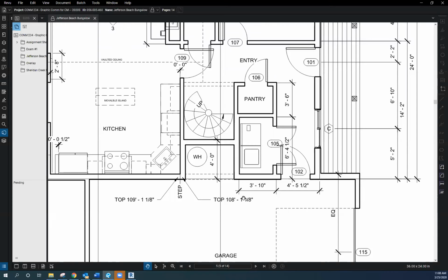The thing that's different about this wall is how the wall is constructed itself. Generally speaking, because we do have an occupancy separation, or occupancy use change, from the main part of the house to the garage, we have to build this wall with a fire rating. In most current single-family residential, that wall rating would be a 1 hour wall that would be built with 5/8 inch drywall on the garage side with 1/2 inch drywall on the inside.